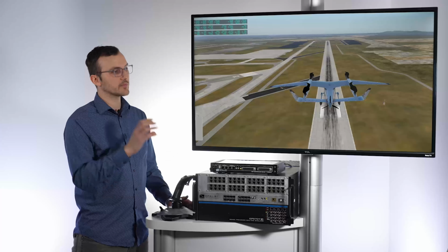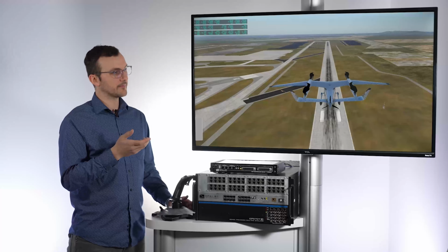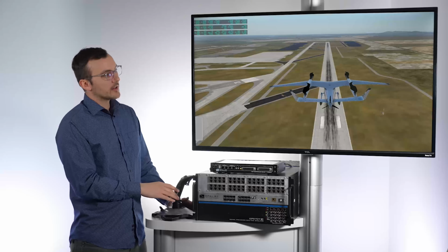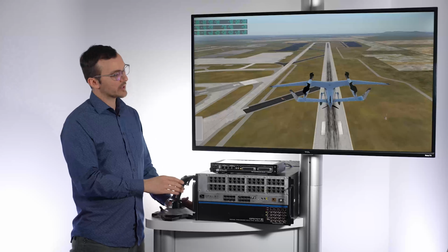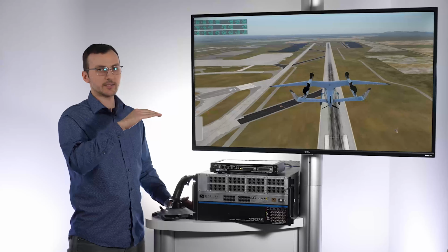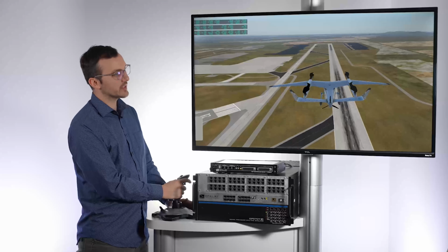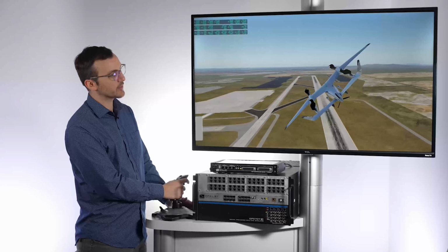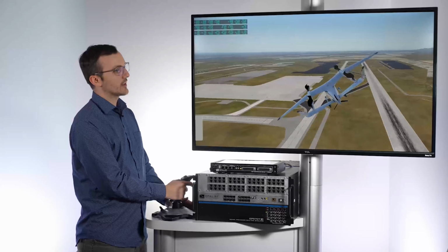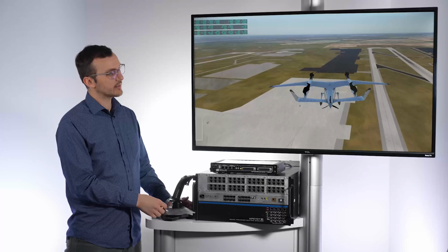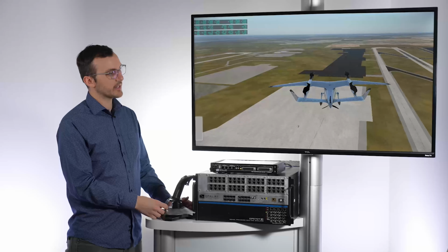This will effectively turn on the 5th motor, and this should push the airplane forward. At this stage, we're flying forward and it's keeping a constant height, and we have control over the airplane. We should take a slight left turn. Same thing for the right side. We can now switch back into vertical mode, and we're going to try and make a soft landing.